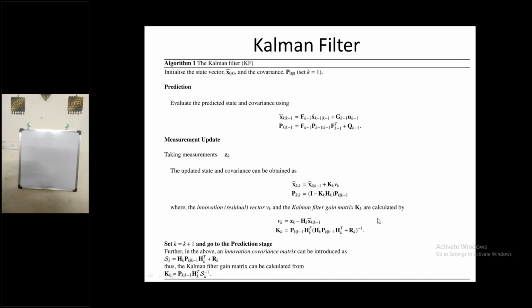So for simulations and for papers, if you choose RK very small, the results will look very fine. But in a realistic situation, it is not so. You have to ensure that whatever RK you give reflects the sensor noise. Just for the sake of it, you cannot take a smaller value. If you take some small value, it will work fine in simulations or in simple cases, but it will fail in real life applications.